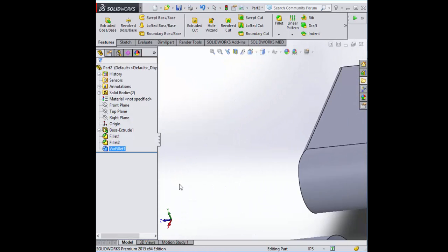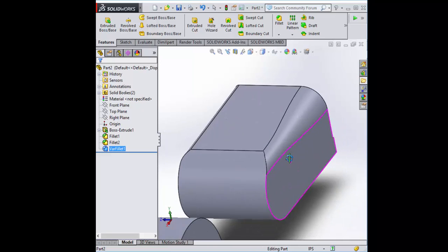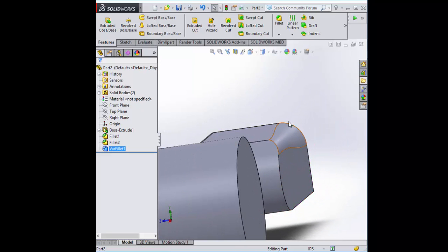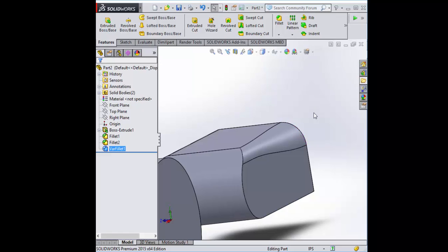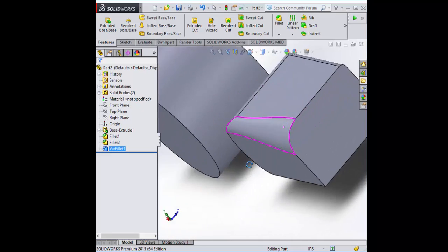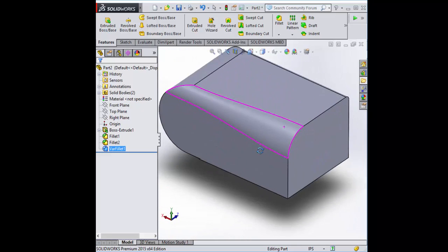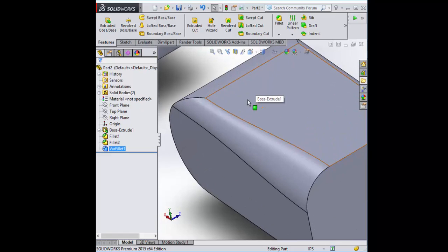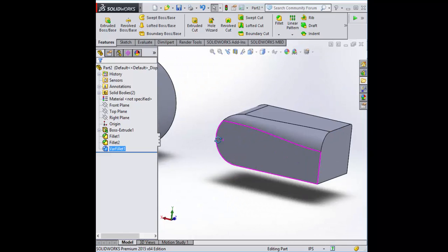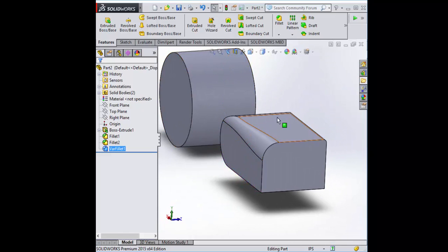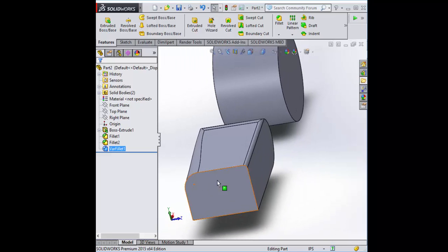You can manipulate these to create very complex fillet types in case you have a small part that you want to open out into a larger part or smooth down. They can be aesthetic or they can be structural to remove stress concentrations, which you'll learn about if you go pursue an engineering degree. So that's a variable radius fillet. They don't always have to keep the same curvature.